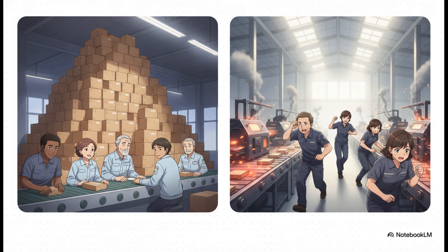Think back to our car factory example. With a level production strategy, you produce vehicles at a steady, constant rhythm. It is fantastic for workforce stability, but if demand for SUVs suddenly drops, you're left holding massive, expensive inventory. On the flip side, if you chase demand, you are frantically scrambling to adjust your output to match exactly what the market wants, this very second. It keeps your inventory footprint low, sure, but it creates a high-stress, overtime-heavy environment for your workers and your machinery.